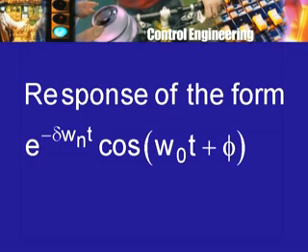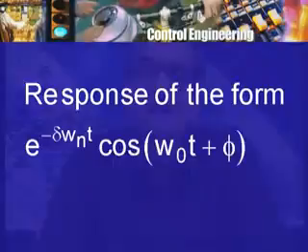And of course, I do not have to remind you, because you will notice from this s plus delta omega n that there is going to be an e raised to minus delta omega n t multiplier for the response, and therefore the time constant will be the reciprocal, 1 by delta omega n. So, if delta is small, the time constant will be very large, the oscillations will settle down very slowly, and from a practical point of view, one does not want oscillations to continue for a long time, because the system itself may not be operating for a very long time.